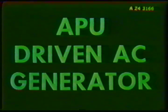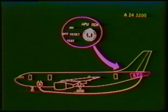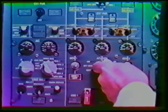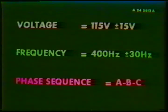Another possibility of supplying the aircraft with AC power is the APU generator. The APU generator is identical to the engine-driven generators with one exception. It does not require a constant speed drive. An APU generator selector controls the operation of the generator within the same parameters as the other generators.